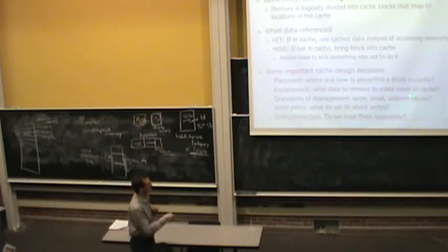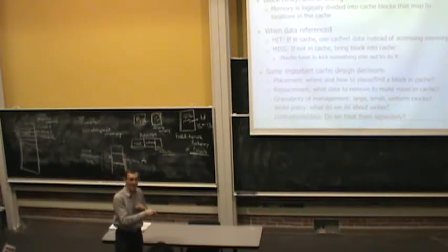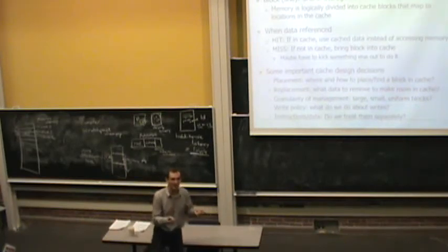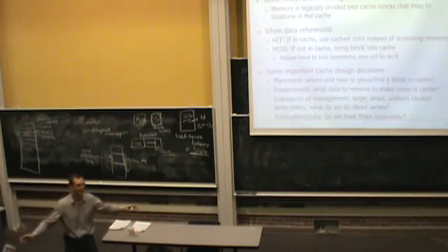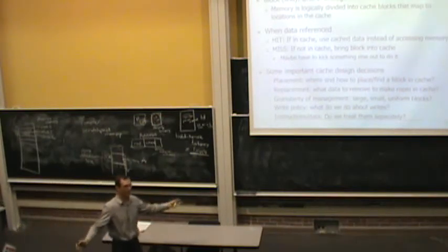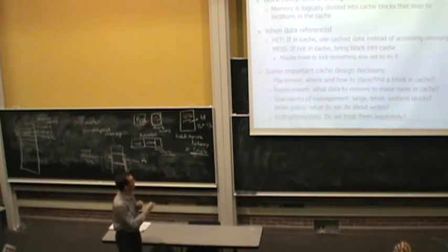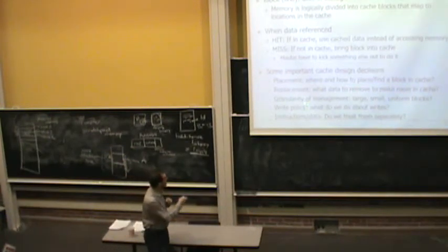But you can stretch your imagination a little bit. This is actually not true for software caches. In hardware, blocks are usually uniform. In software, for example if you do web caching, you have files of different sizes, so you could cache things of different sizes in that case. But in hardware, you want to preserve regularity, although people have proposed designs with multiple different block sizes in hardware too.